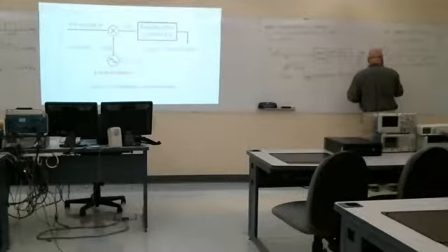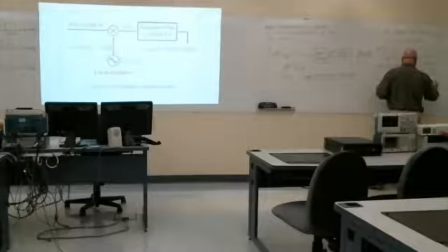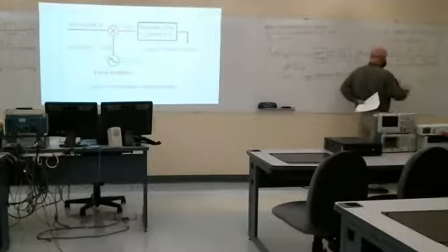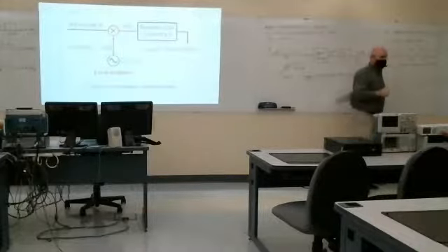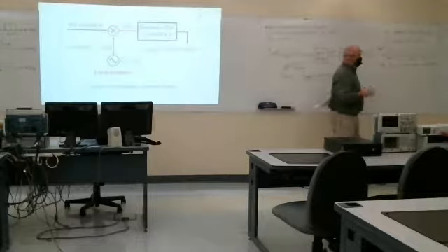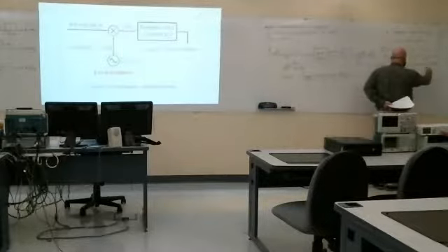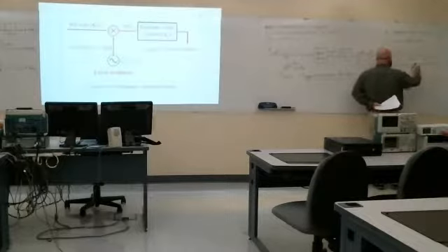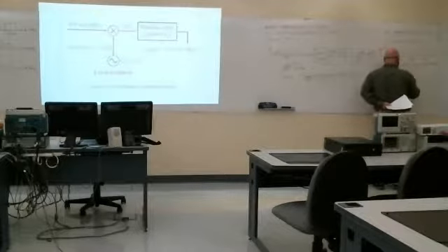So when that is mixed with our RF, we'll get out the sum and difference frequencies in each case. I'm only going to look at the difference frequency. The intermediate filter will actually filter out everything else. But the difference between 1475 and the 1020 is 455.